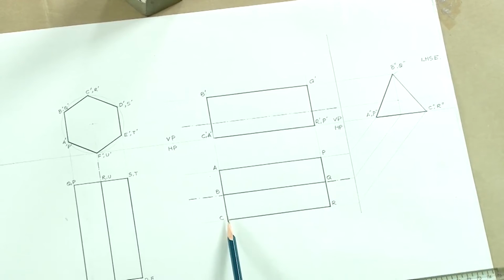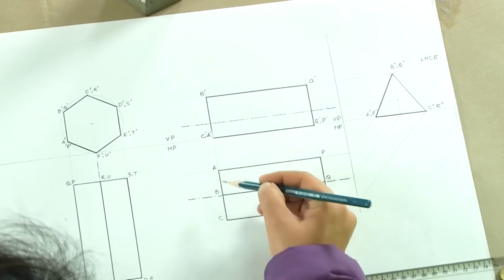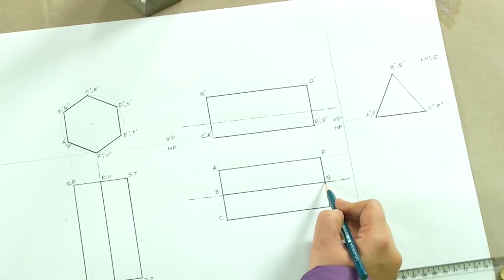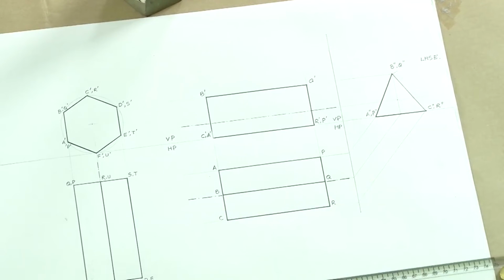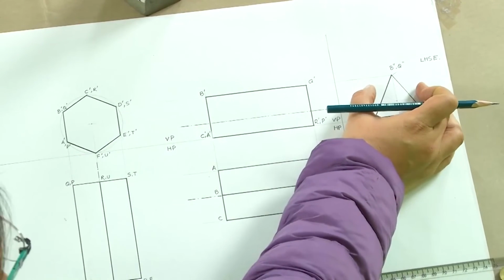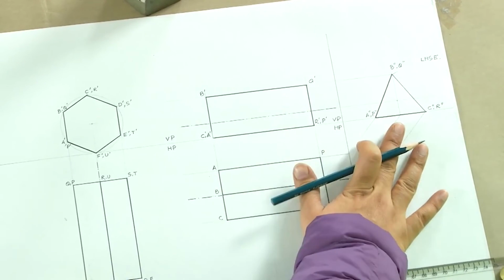We could have drawn it directly here, but that would have been a derivation, not a drawing derivation, where we could have just drawn the full size of the base and then just divided, because that is what we know as a general geometric understanding. So we could have done that, but we should always avoid it, and we should start from the plane where we are seeing the true shape, the true dimension.